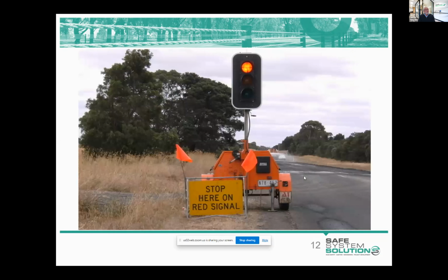Non-compliant signs: black on yellow, that's our normal roadwork signing. So I gather that's what the company was thinking. But that's a regulatory sign. That should be red writing on a white background. So again, as auditors, we need to ensure that the signing itself, any regulatory signing, is correct.